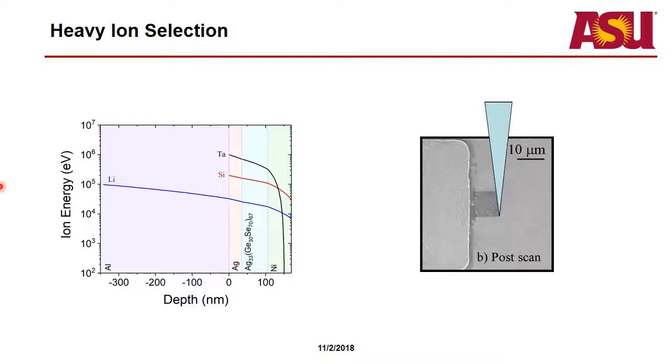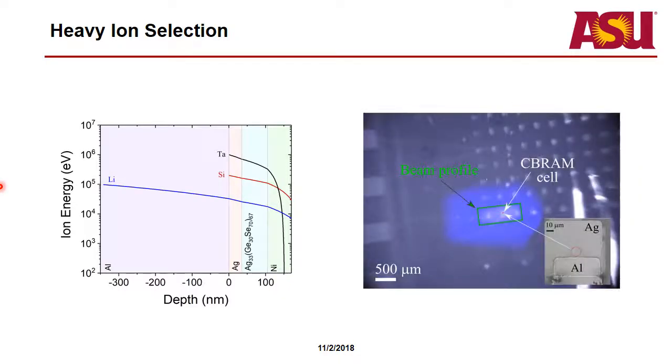But for the tantalum ions, we use the broad beam configuration at Sandia. That puts about a 1 millimeter beam on the device, and so obviously the beam's going to be hitting multiple devices. Depending on how small of a die you use, that's not the most ideal setup. But for our die, we had pretty big die, and plenty of devices, so we can move around to different devices on a single die without having to worry about overlap from the prior exposure.